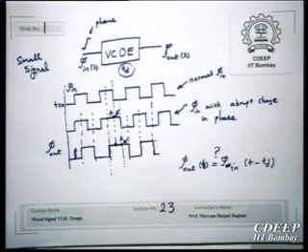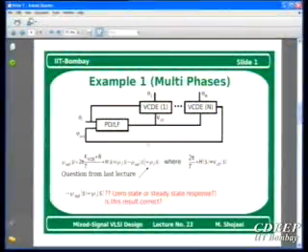Okay, so now to see how this behaves, there are two things. One thing will be, practically, how this loop behaves. Suppose I apply a change. This phase still has not changed. This phase doesn't change abruptly. It will continue as it was. Therefore, here an error will be generated. This error will change VCTL. And because of VCTL, now the delay of this delay element will change.